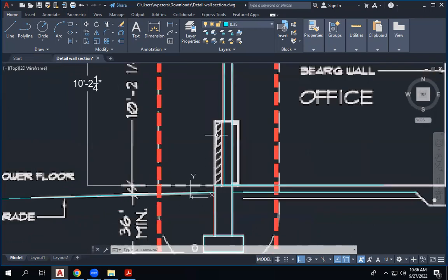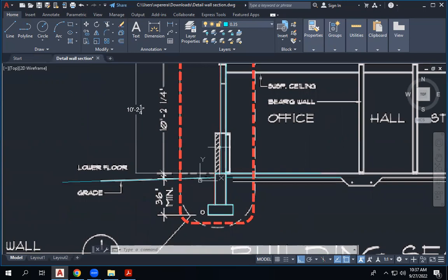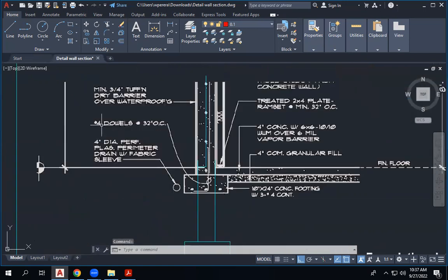It's also showing another brick wall that they have done outside. So we don't need the brick part at all? No need. This is to give the building a nice elevation. They just extended out some detail there. So we will not consider this one. We will have this offset here. Now inside we will have these three layers.